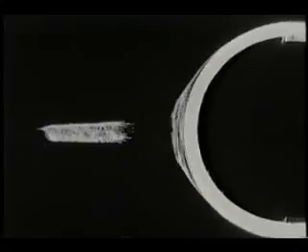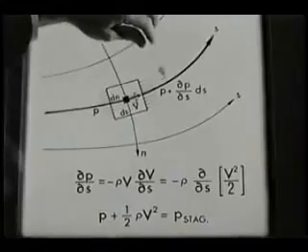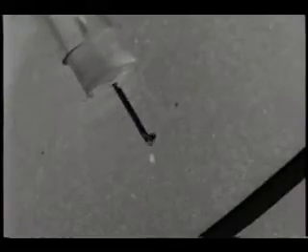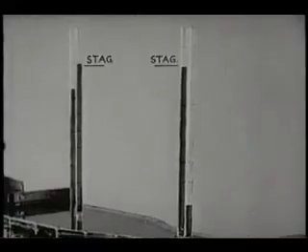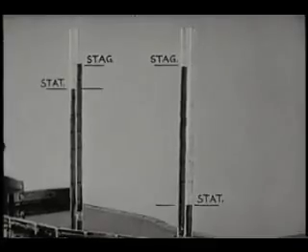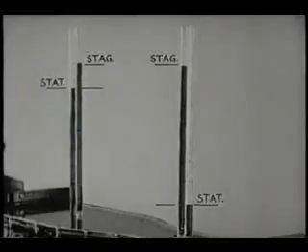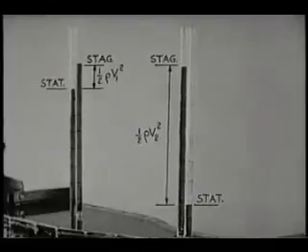The stagnation point is put to practical use in a pitot tube. The hole at the nose measures the stagnation pressure of the particular streamline reaching the hole. We've placed pitot tubes at the upstream and downstream cross sections of the contraction, and these are the static pressure manometers we had before. The difference between the stagnation pressure and the static pressure is the local dynamic pressure. So this is a way of measuring velocity.